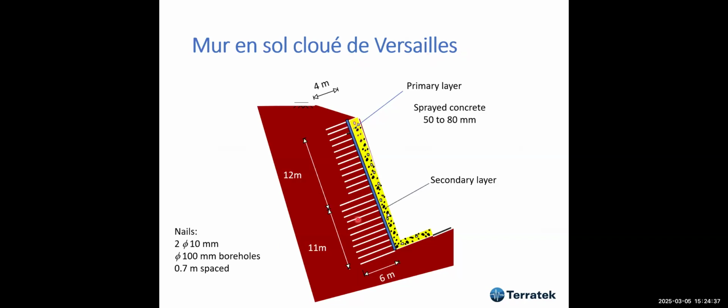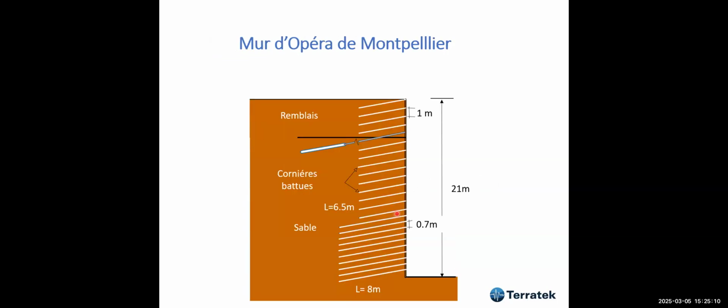And as you see here, they have very short nails, not like 6 meters, and here 4 meters, so very short. And they did as they did in tunnels. And why? Because these techniques seem to have developed from tunneling. And they have the primary layer, shotcrete layer, and then a secondary layer of concrete. That's the idea, okay, at the time. Probably this comes from tunneling engineers.